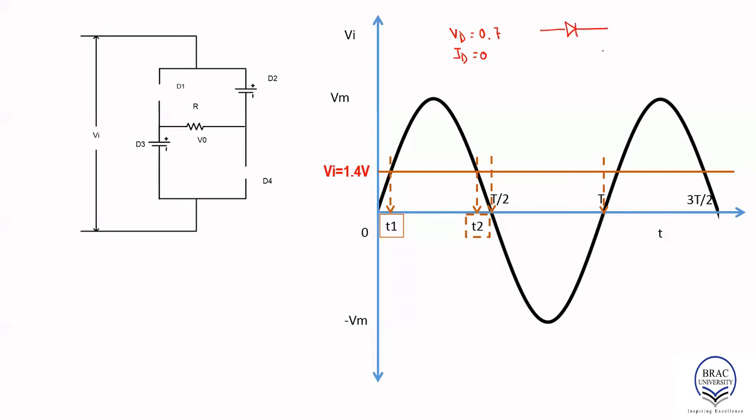if I draw the simplified diagram, so D2 and the resistor and D3, plus minus Vi. You see, this is how it looks like. Positive terminal, then D2, then the resistor and D3. So if you want to determine the transition state voltage, we have to pass through 2 diodes, so the transition state voltage will occur at 0.7 and 0.7.